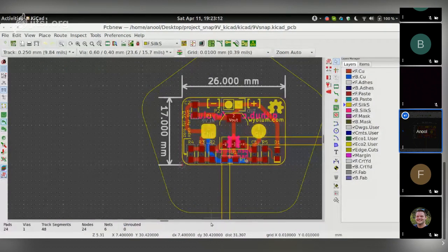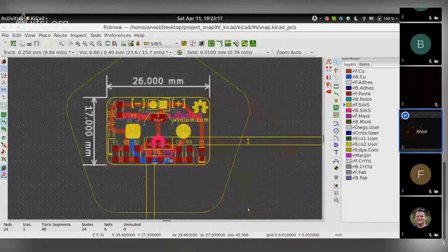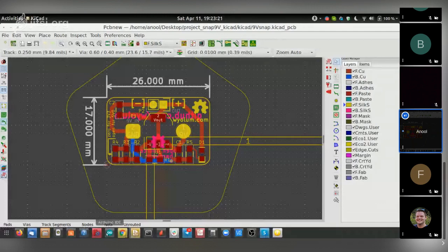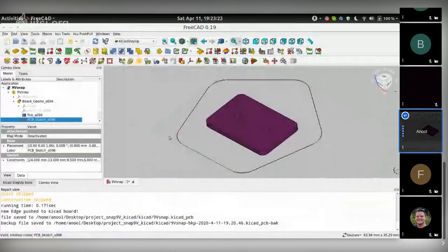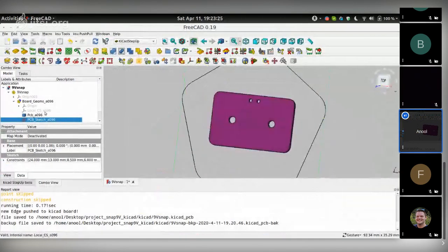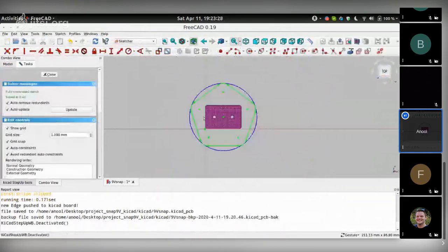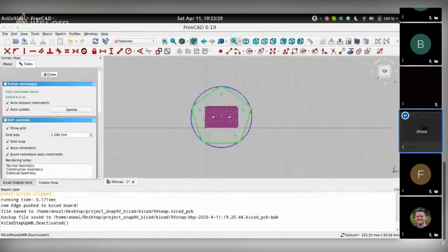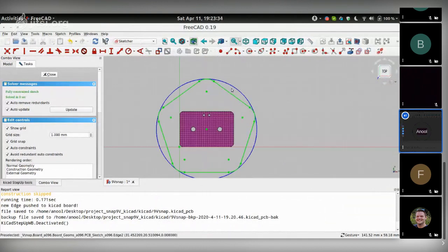So what I could have done, which I didn't, was move this whole pentagon, and instead of having chosen the radius of the enclosing circle, I probably could have chosen the length of the side as a defining constraint.